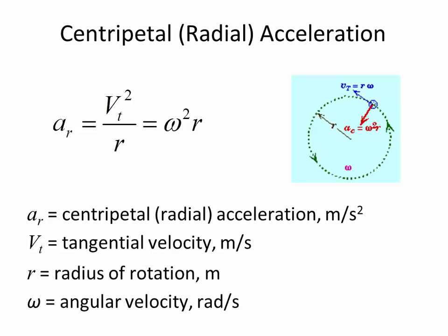Okay, so local is the change in velocity with respect to time. What kind of flow is varying with respect to time? Steady versus unsteady. So when there's local acceleration, we have unsteady flow. If there is local acceleration, that causes unsteady flow. If there's convective acceleration happening, then what kind of flow have we got? Non-uniform, which is the change of velocity with respect to position. Good. That's a good review.